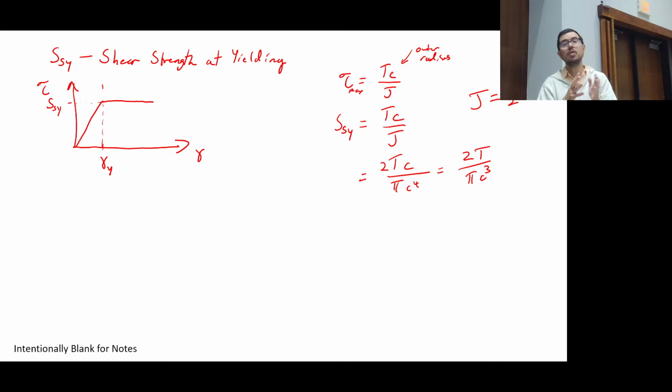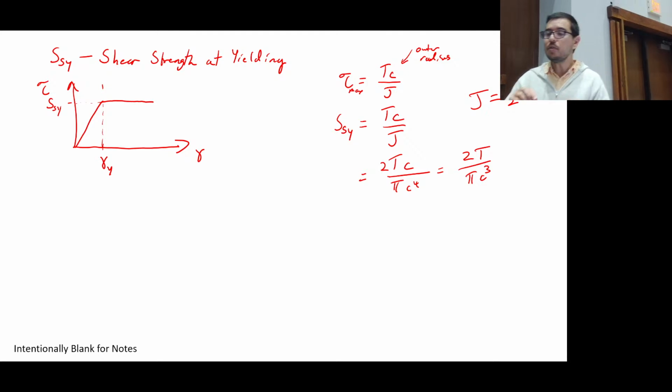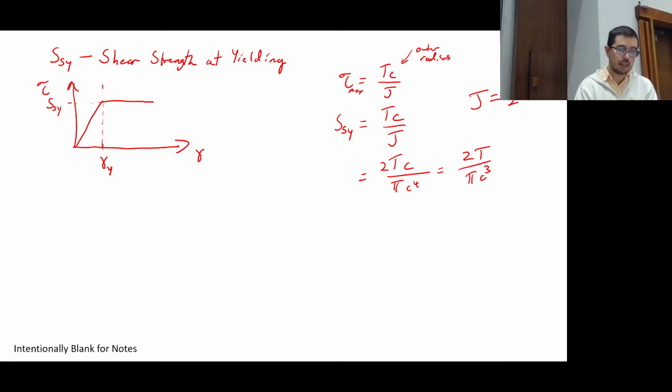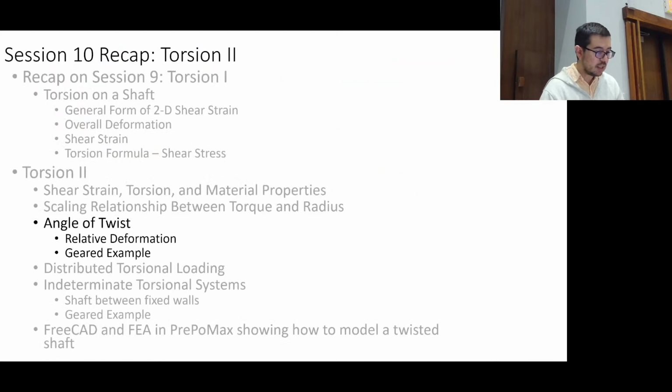Stress concentrations, and you'll cover this in DMC. Stress concentration is just a fancy way of saying corner. Internal corner that causes a higher stress than you anticipate. So you try to avoid sharp corners. But in reality, for most problems with static loading, that is not a huge problem. You don't have to think about the stress concentration factor too much. And we're doing static, so we're happy, right? But when you have fatigue, or impact, you will be more concerned about these correction factors. Anyway, that'll be next semester.